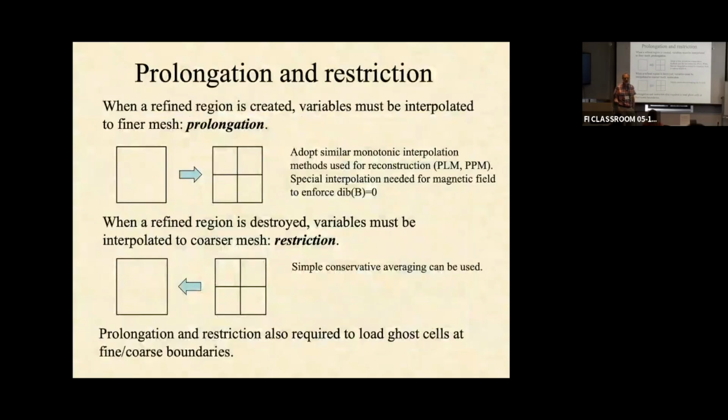You have to try increasing the number of levels you're using and see whether or not the solution changes. It goes hand in hand with the refinement criterion, because the number of levels you use and the refinement criterion can be degenerate. Changing one might change the other. There's no mathematical proof you can use for a given problem to know what you need. You just have to experiment, know your physics problem, know what you're trying to measure and what it depends on, and make sure you're using that. Not the best answer, but that's the way it is.